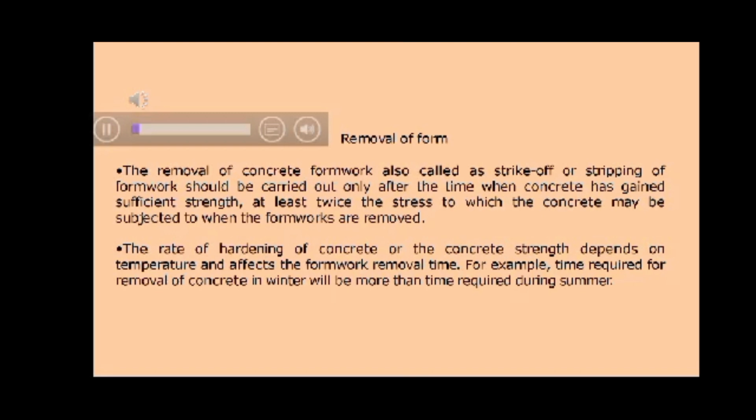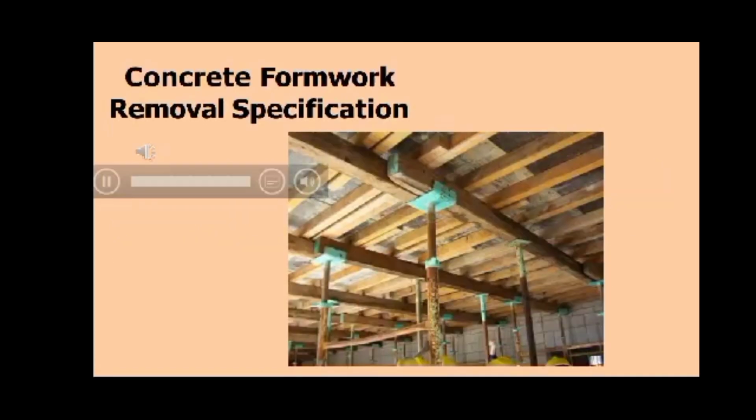So let's proceed to formwork removal. The removal is called strike off or strike out, done only after the time when the concrete has sufficient strength. The concrete strength affects the form removal time required, and the time required during some conditions. So these are the specifications.